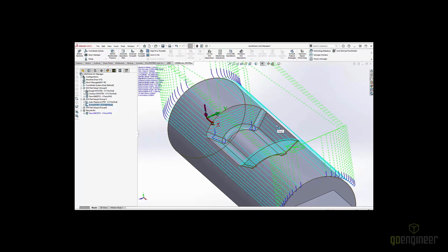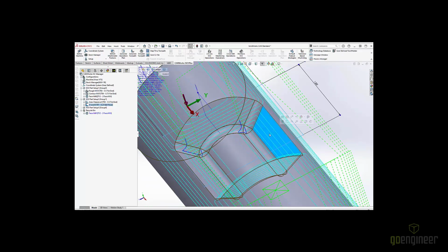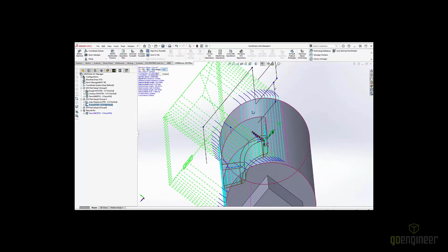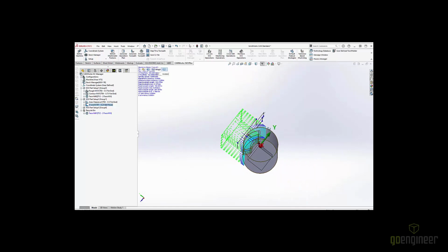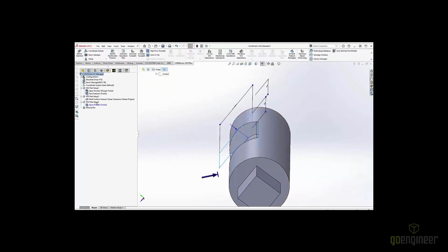Now, there's other steps I could take to get around this. For instance, the walls in this multi-surface feature, this wall particularly, the best thing we could do to get a good surface finish on that is line the end mill right up with it and do some true side end milling, right? Have this part oriented in a vise in this manner so that the end mill can come sweep right across that.